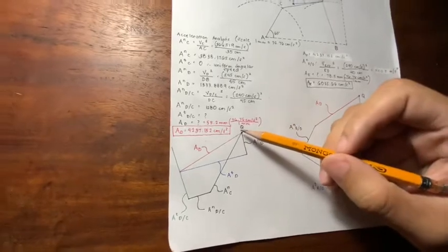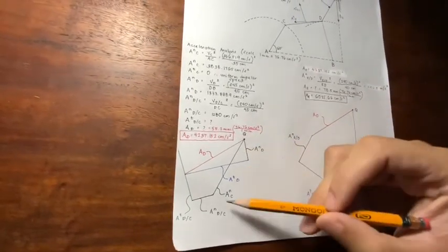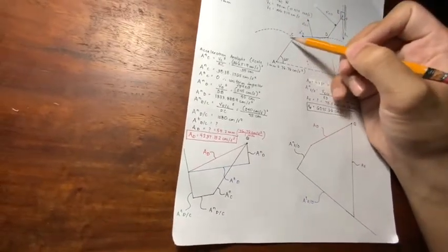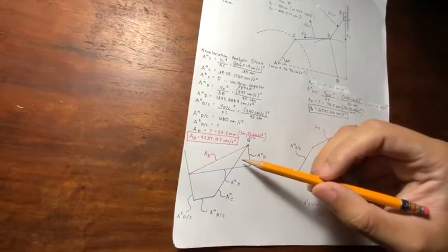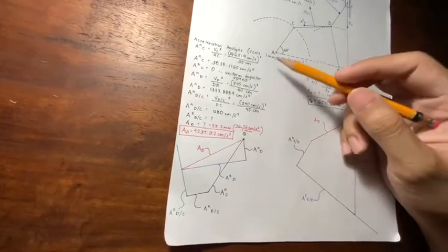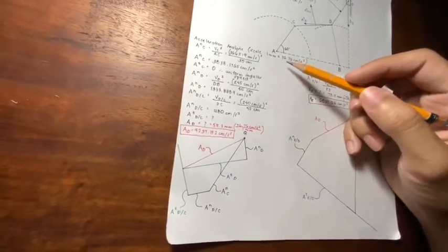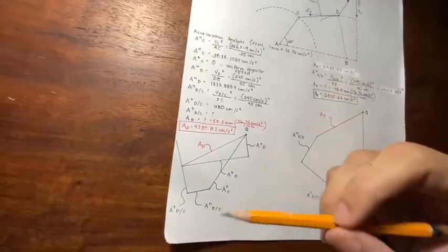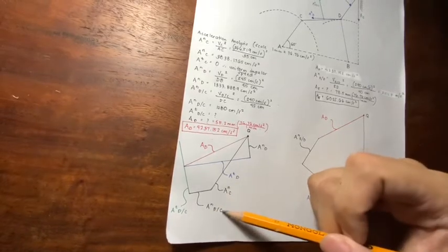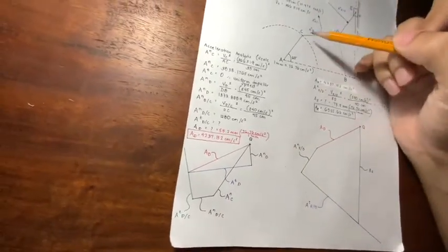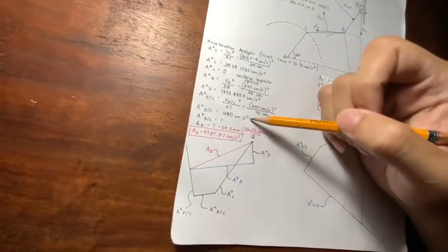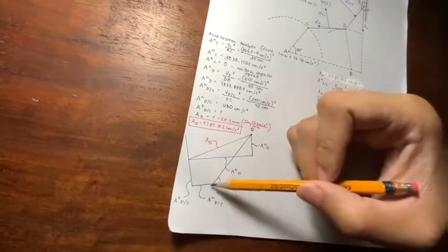Now we have our arbitrary point Q. We will start off by drawing the normal acceleration at point C, which goes in the direction of link AC. And with the magnitude of this, we can now draw this using our scale of 1 millimeter equals 76.76 centimeters per second squared. From there, we will now draw our acceleration normal to DC, which goes along the direction of link DC, and has this magnitude again. So we will now draw that.